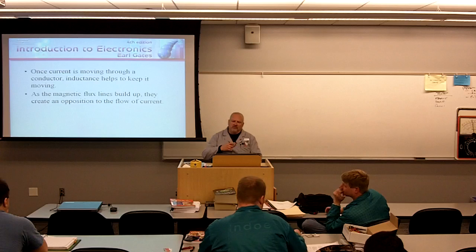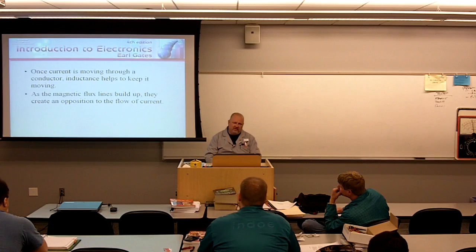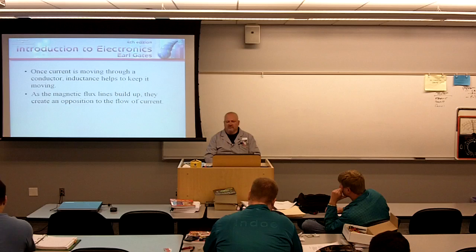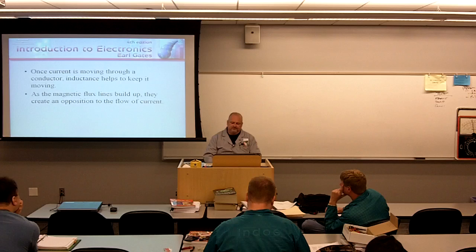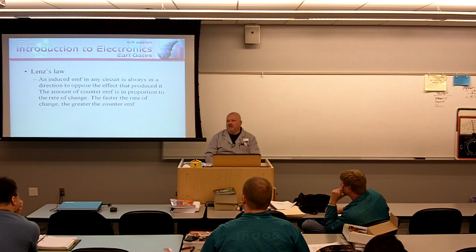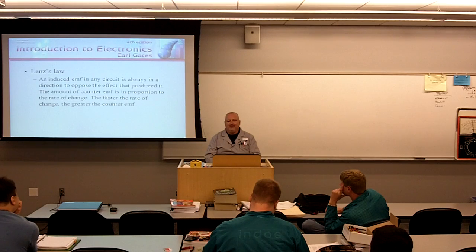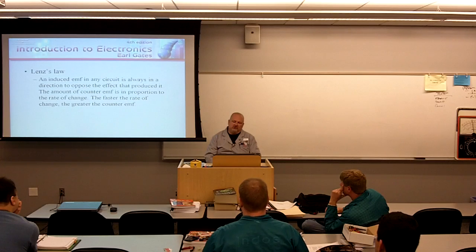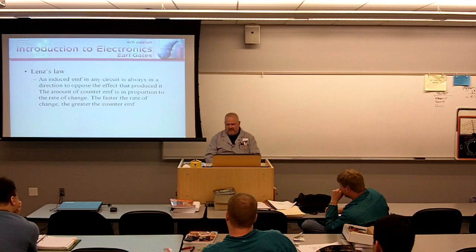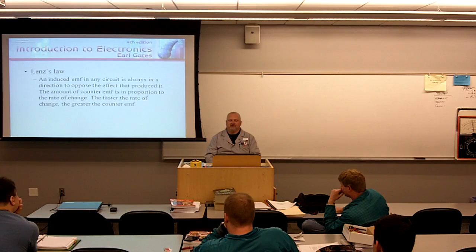Now, once current is moving through a conductor, inductance helps to keep it moving. As the magnetic flux lines build up, they create an opposition to the flow of current. Lenz's law talks about that. Lenz's law states an induced EMF in any circuit is always in a direction to oppose the effect that produced it. The amount of counter EMF is proportional to the rate of change. The faster the rate of change, the greater the counter EMF.